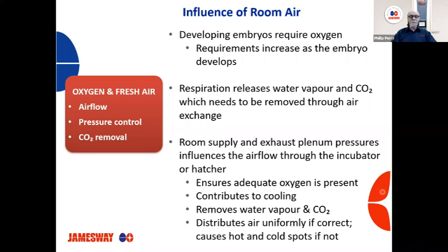A lot of times I'll visit hatcheries that may have an overheating problem, which may be a factor of either room temperature or their chilled water temperature, but they crank up room pressure, and you think the machine is running cooler, but because we're running air faster through the machine, there's less mixing, and often the air just isn't distributed uniformly.